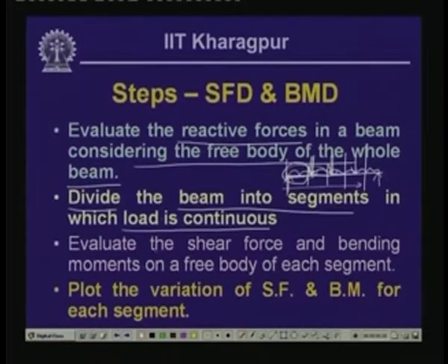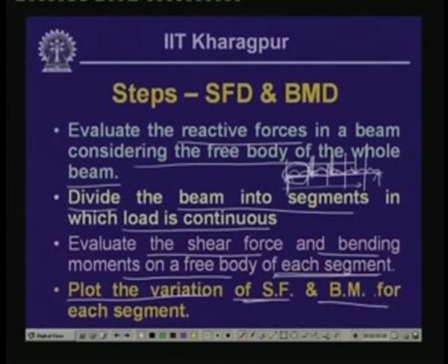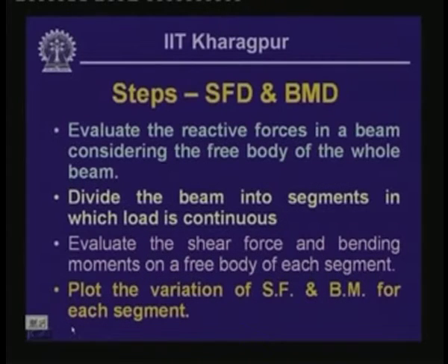So, this is what is mentioned here: evaluate the shear force and bending moment on the free body of each segment, and plot the variation of shear force and bending moment for each of such segments. Once you do that, you will get the shear force diagram and the bending moment diagram of that particular beam. So, these are the steps one has to go through to draw the shear force and bending moment diagram.